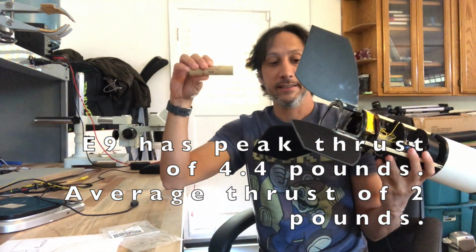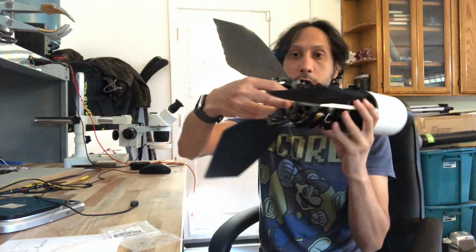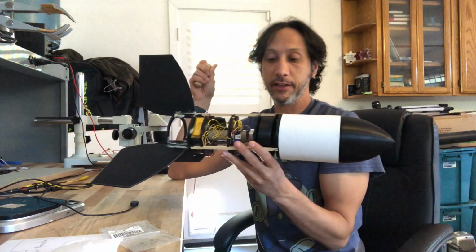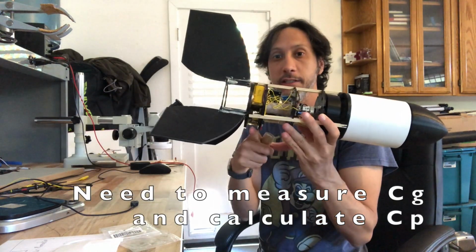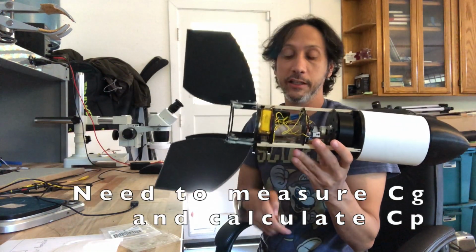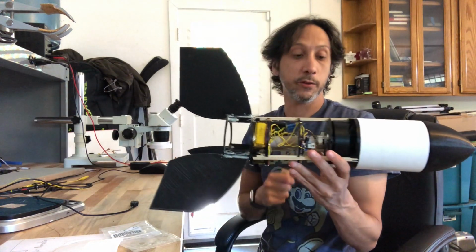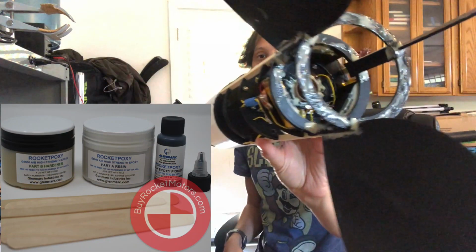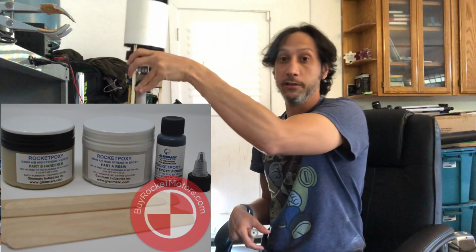It runs on these Estes E9 engines, and I'm going to have to jam it way up there, hopefully leaving it about the center of mass. I still have to measure that to see where the center of gravity is. Hopefully it's right about here, in which case the sideways torque from this motor won't have any effect. But there it is. I use rocket epoxy all over the place. I love it. Use it even around the house.